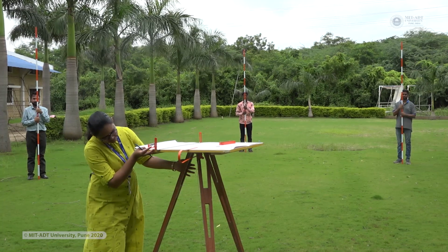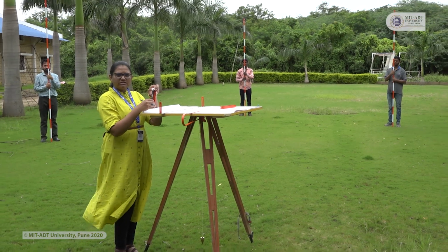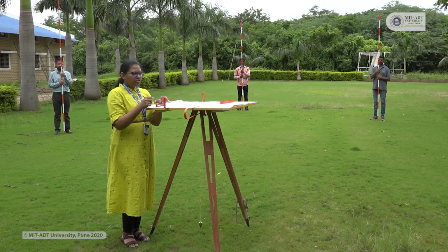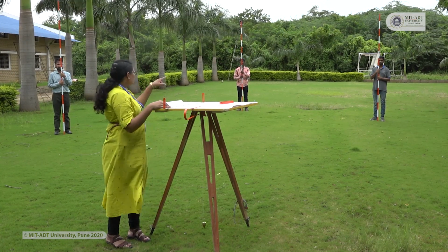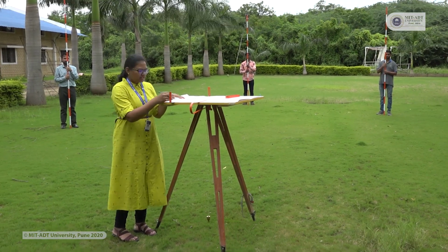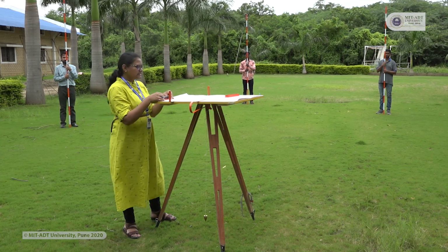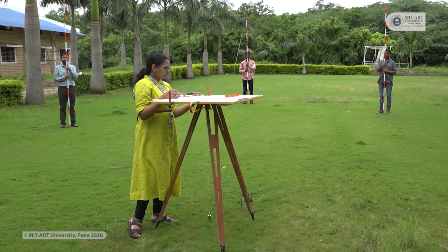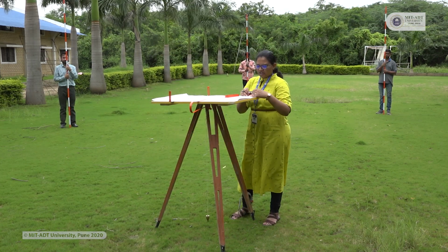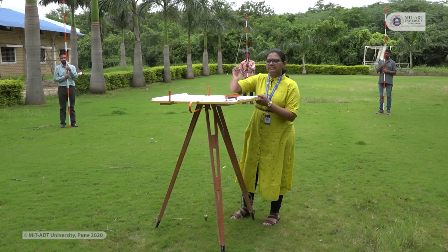After setting up this plane table onto the tripod stand, I will keep this level tube at different points. At these different points, we have to check that the bubble is merged in the center, and you have to fix this station point such that all the station points should be visible from our station point. Before starting the practical, I will check the levels at different corners. At this corner the bubble tube is at center. I will check at this corner also. Again the bubble tube is at center. Similarly, I will check for this corner. Again the bubble tube is in the center, and last I will keep the bubble tube at this corner.